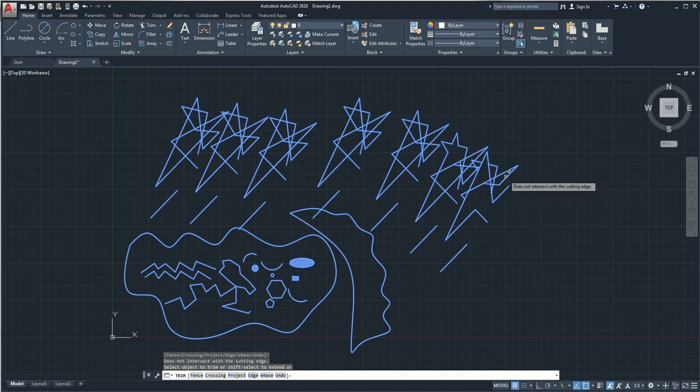So this is a very important issue in the trim feature. We should have something like intersected lines or intersected features to be trimmed. We couldn't trim this one because this is the start point and this is the end point of this line, and it's not intersected with any other lines, so this one couldn't be trimmed, by the way. Okay, so this is the trim feature.